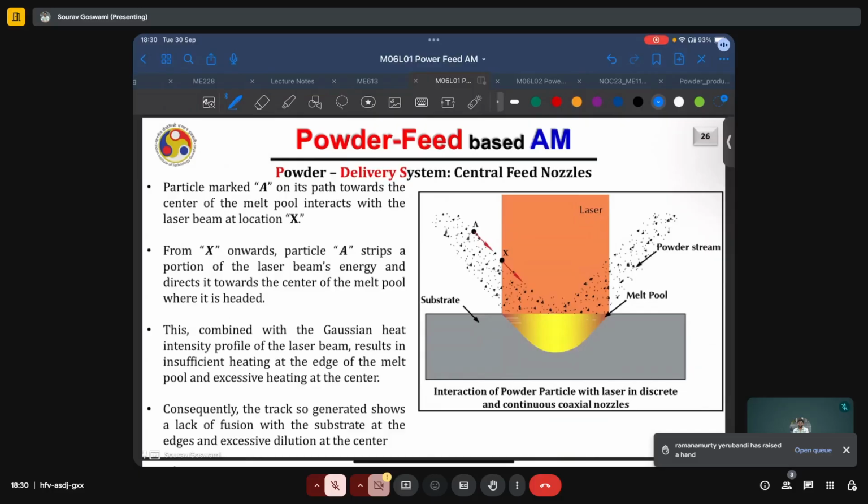So if we are just printing with simple geometries, it's elementary. But if you are printing a complex or intricate geometry with overhanging structures, we resort to the use of multi-degree of freedom tables, such as a five-axis CNC table, or multi-degree of freedom deposition heads, such as robots.